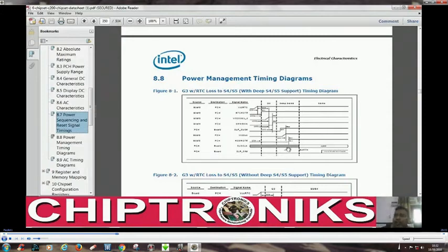So in the new ACPI, in earlier kinds of boards, in the advanced configuration power interface, the power sequence was divided between G3 mechanical off, where the RTC section turns on, and after G3 mechanical off, it was S5, then S4, then S3, and then S0.